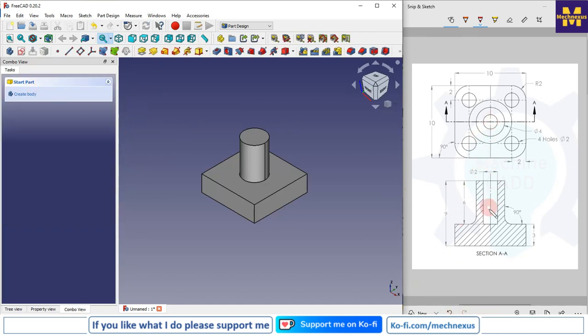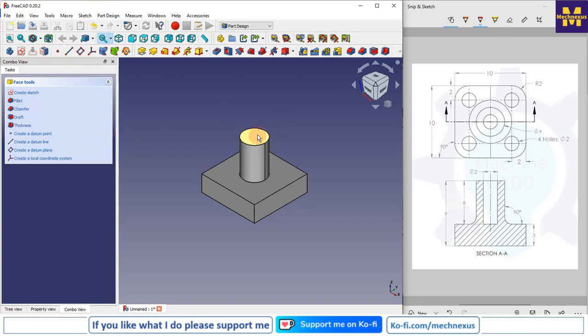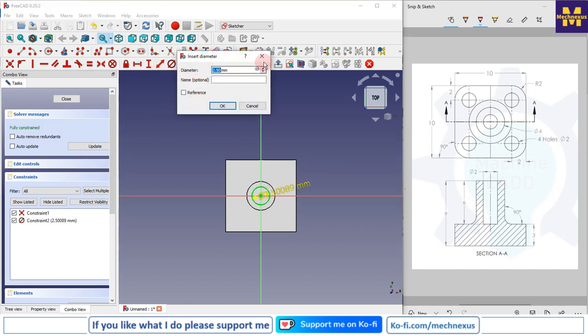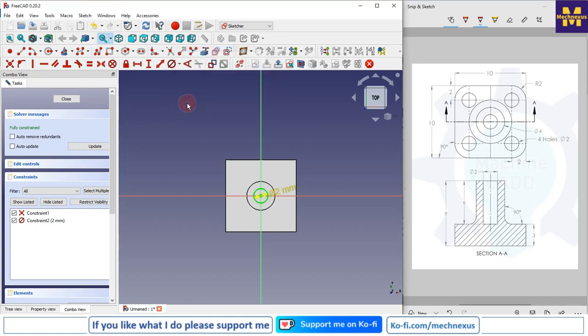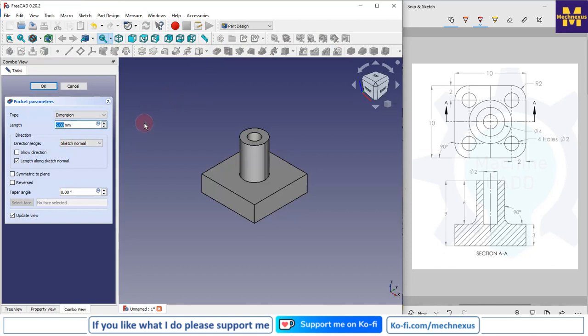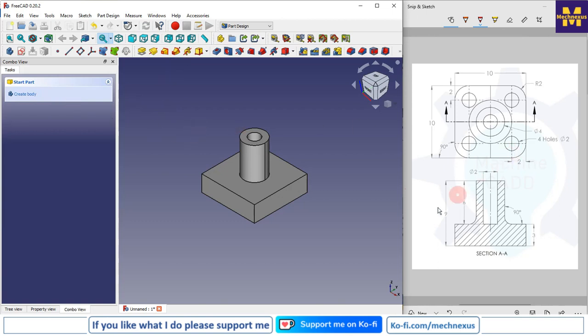Now we can see that there is a cut of diameter 2 for a depth of 6 mm. So I will again select the face of the circle and create the sketch, and on the top I will draw a circle and give it a diameter of 2 mm, and I will close it. Here I will select the cut, and the cut depth would be 6 mm, and I will say OK. So the overall shape of our part is made.